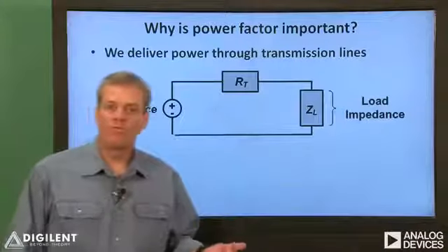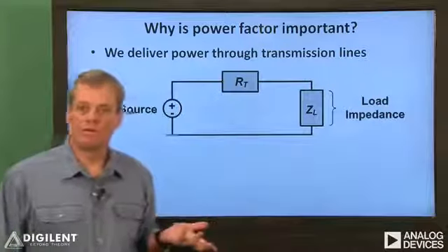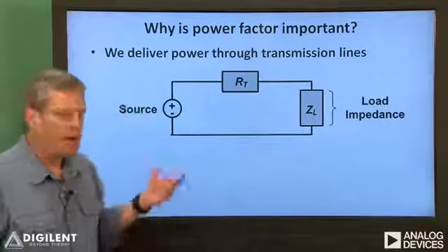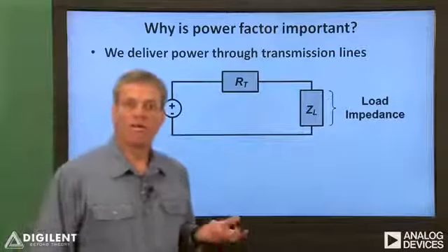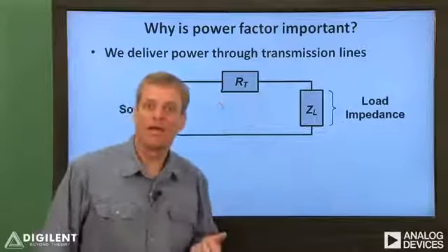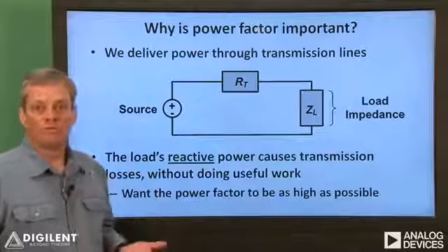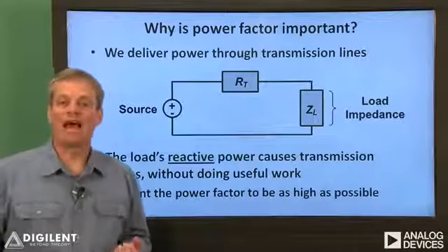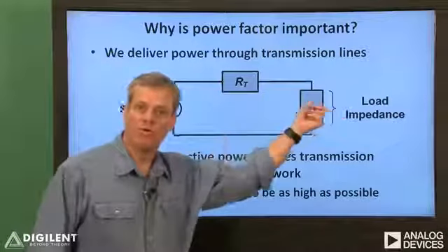To see why the power factor is important, let's look at this representation of a typical power delivery system. We're generating power with some voltage source. The power is delivered to our load via a transmission line which has some resistance R sub T. The average power delivered to the load is used to perform useful work. However, reactive power delivered to the load is simply traded back and forth between the load and the source.